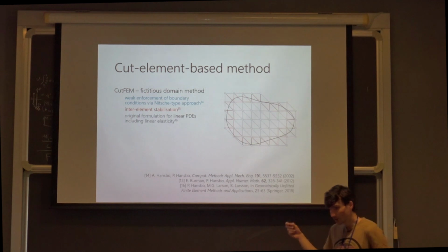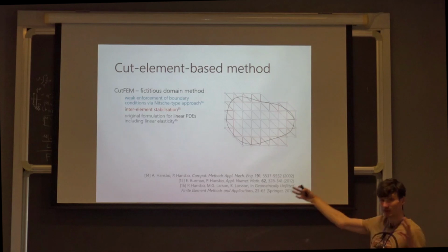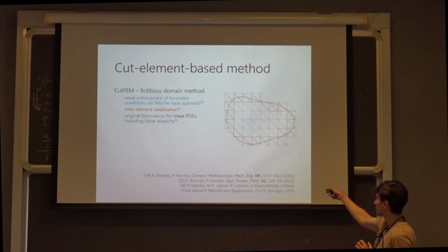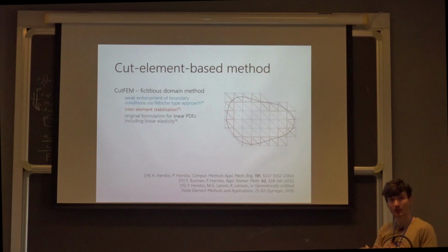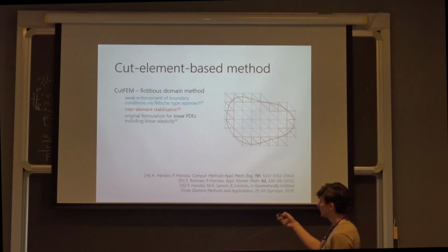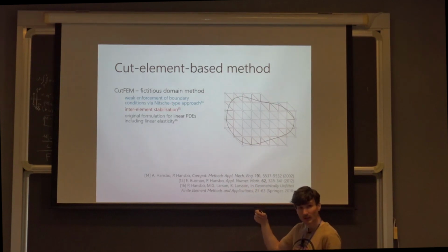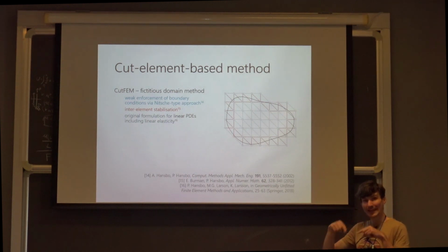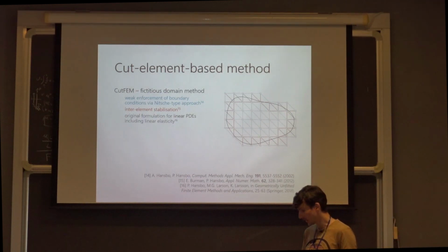CutFEM is a fictitious domain method, which means that we have a finite element mesh which spreads outside of the geometry of our body. Here I'm just drawing the boundary of the body, but we handle the interface exactly the same as the external boundary. There is no difference in that. The CutFEM method is characterized by weak enforcement of the boundary conditions using Nitsche's method, and by inter-element stabilization, which is enforced on the internal boundaries of the elements which are cut by the interface. Originally it was formulated for linear PDEs, including linear elasticity, so that has been done before us.